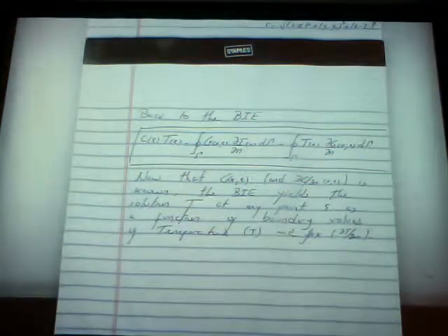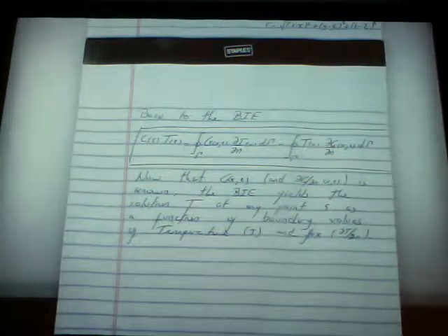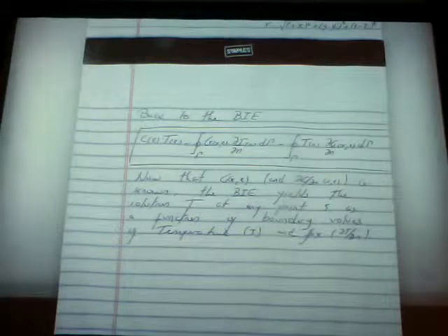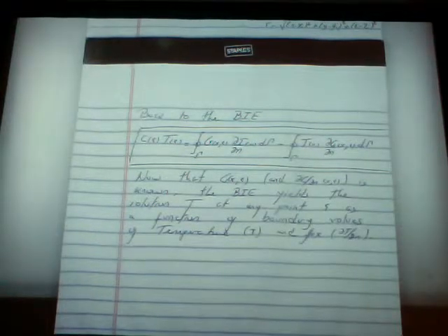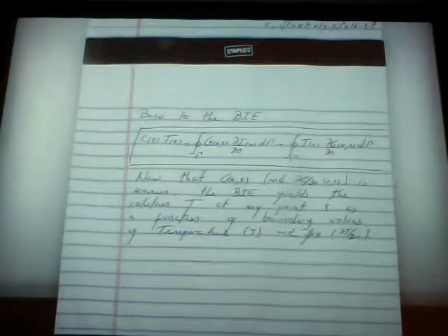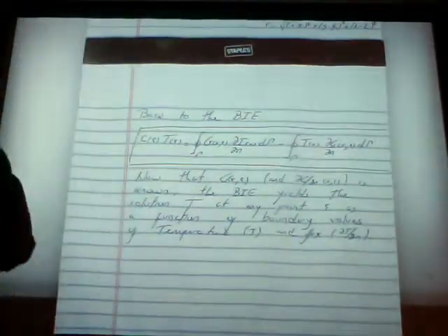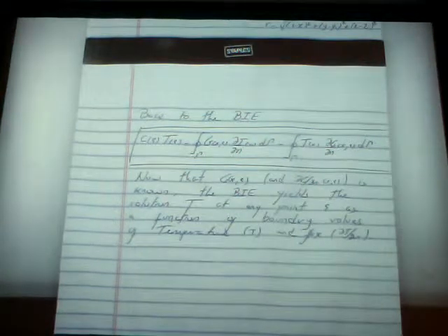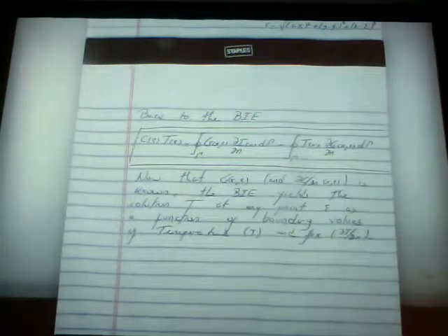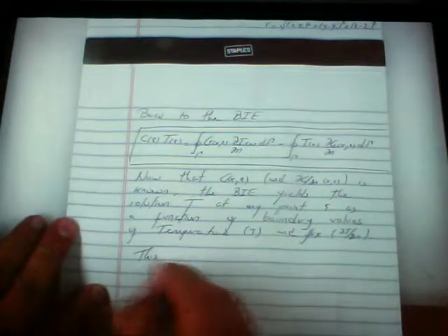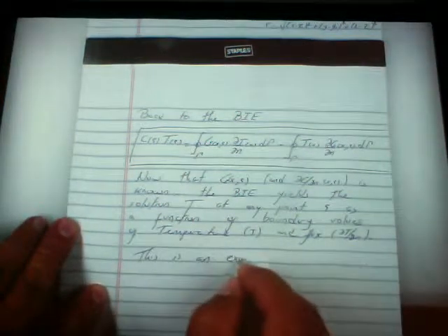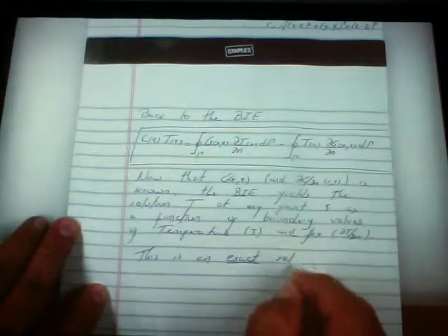So it's just a boundary only relationship. If I know what the boundary looks like, which I should know, right? Even if it's a triangle, now we don't have a problem because I can integrate around a triangle. If I had the T and the dT/dn everywhere, I can know the temperature anywhere I want to. And that's an exact relationship.